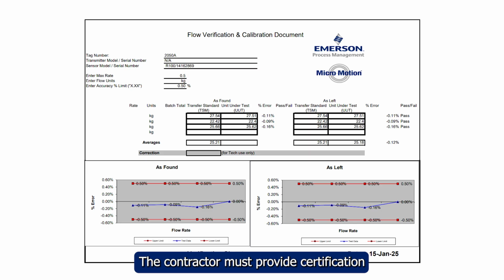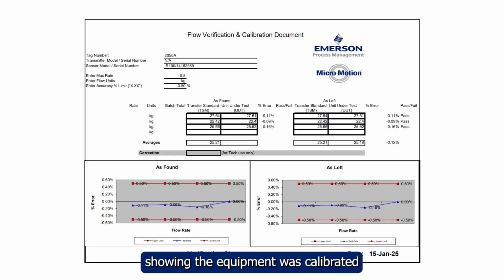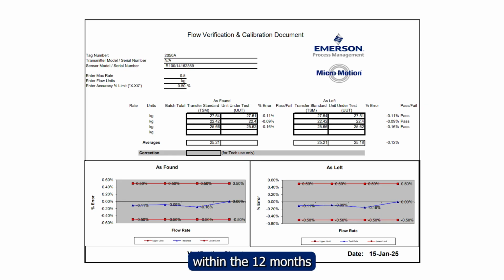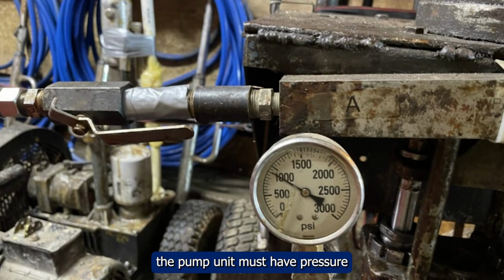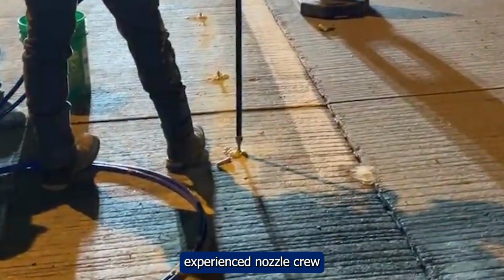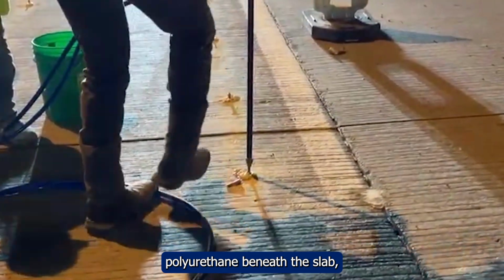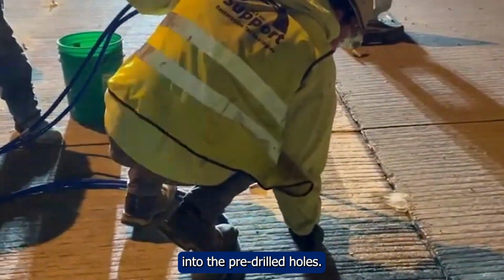The contractor must provide certification of calibration testing, showing the equipment was calibrated within the 12 months preceding the project start. Additionally, the pump unit must have pressure and temperature controls to maintain proper conditions for accurate material mixing and proportioning. Next, the contractor's experienced nozzle crew will begin injecting the high-density polyurethane beneath the slab into the pre-drilled holes.